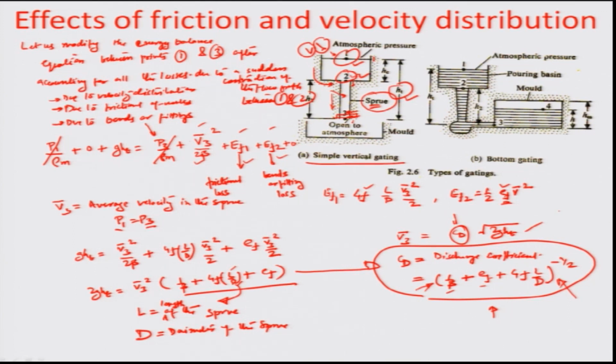Then starting from there and trying to see what is the flow regime, whether it is laminar or turbulent, we can try to estimate iteratively what is the C_d value, so that the actual values of V3 could be slowly converged at, and so with 2 or 3 iterations you are able to come to a point where you can have a perfect convergence of the V3 term while doing calculations for such molds.